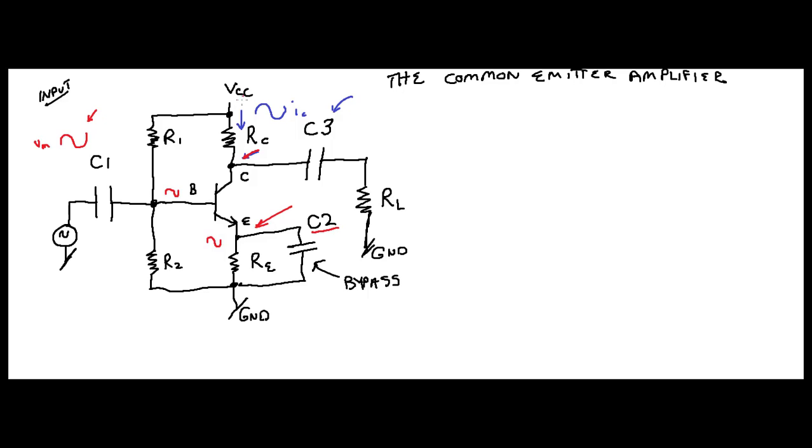Remember, you're starting with V_CC. So V_C, your voltage at your collector, is going to equal V_CC, obviously that's what you're starting off with, minus the drop across R_C, and that's going to equal I_C R_C. And I should have made that a minus sign there. Sorry about that.